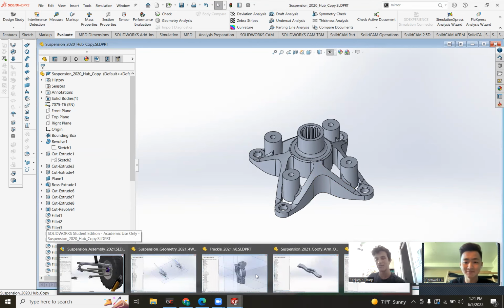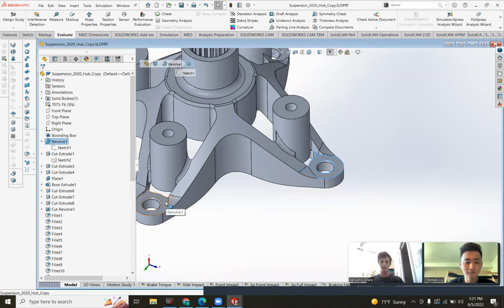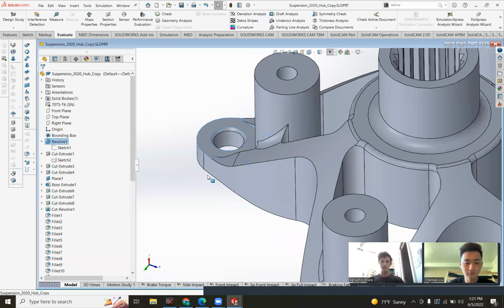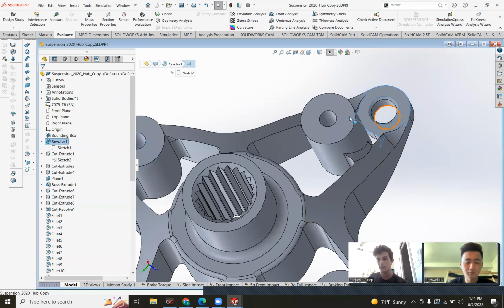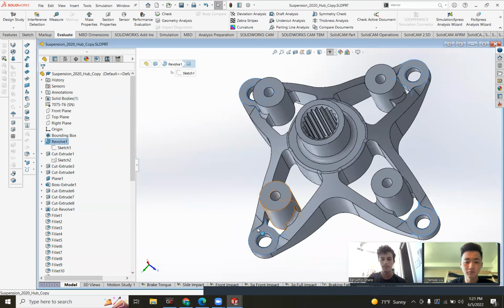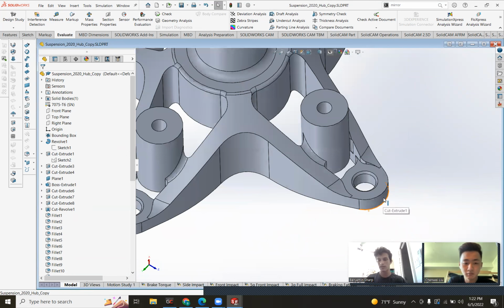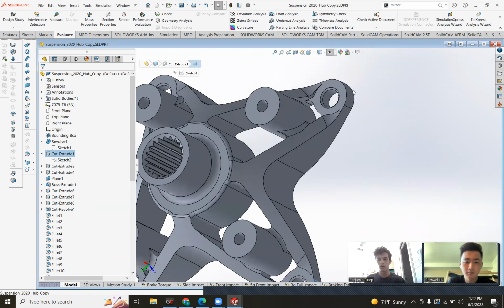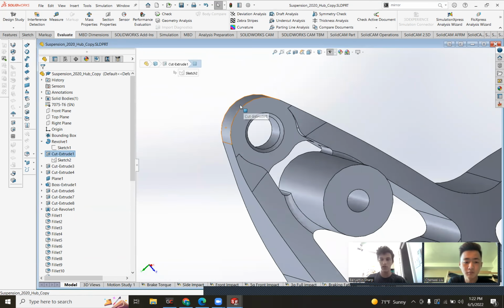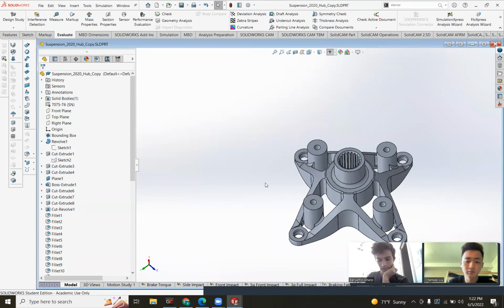But it can always be improved. The one thing that I think is too weak still is this little portion of material. I think it's very thin and it scares me. And that's what has broken in the past. That's where the stud is pressed in. And the one thing you might have to change, if for some reason you can't figure out how to fix it on the caliper end, is that it was interfering with the caliper here and here. But we cannot take material off of this outer edge. So that should be fixed on the caliper side.